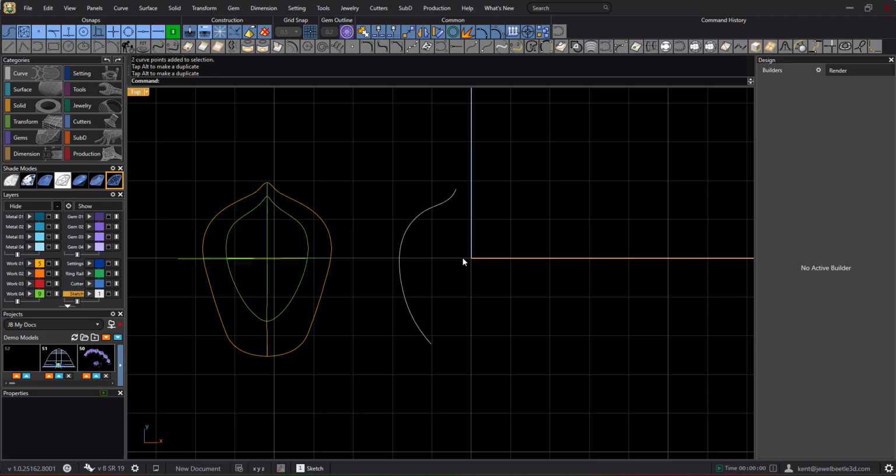But there is that shape, and of course I'm going to hit Control F1. So that's the same as mirror. So rather than do, let's go ahead and delete that. So you might do mirror, and then mirror plane is F4 or 0. And there you go. Shortcut of that is Control F1.